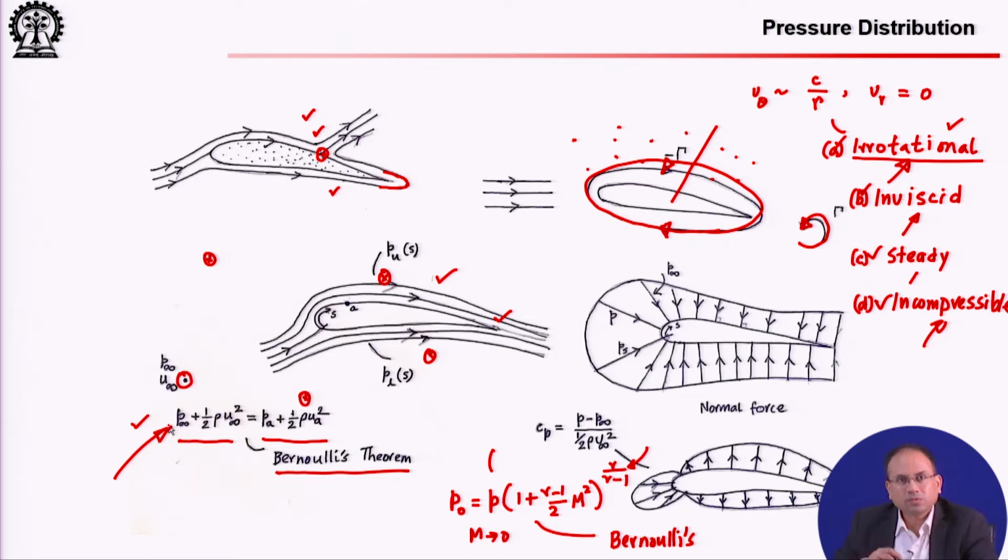To recap once again, in the previous lecture we showed that if a flow field is irrotational, like if all these A, B, C, D are satisfied, then the addition of static pressure and dynamic pressure between any points, here a free stream point which we call the infinity point, and any other point, say point A and point B, you can add the static and dynamic pressure and see that these become equal if all four conditions are satisfied.